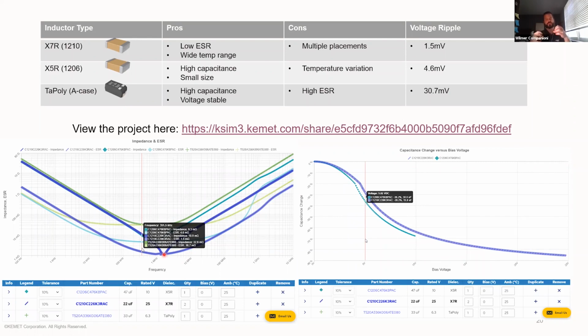A sintering is when those powders, those particles, are allowed to grow together. The particles in a metal composite inductor are actually isolated from one another using this binder and isolating material. And the reason for that is similar to why we have laminations in transformers: to minimize some of those losses due to eddy currents and things like that.